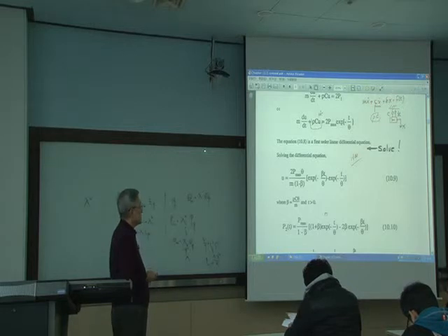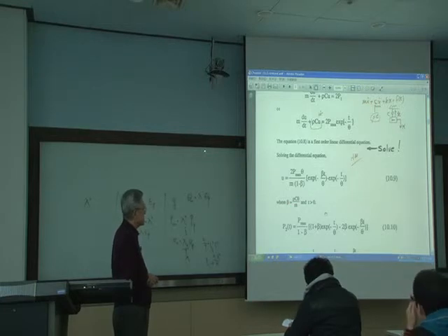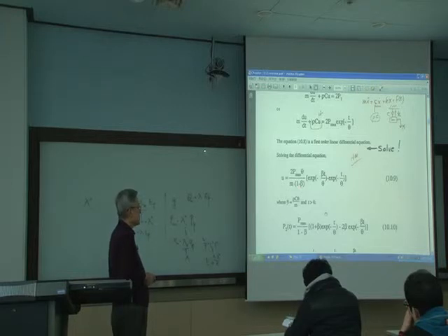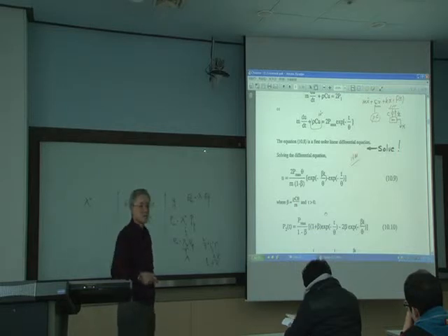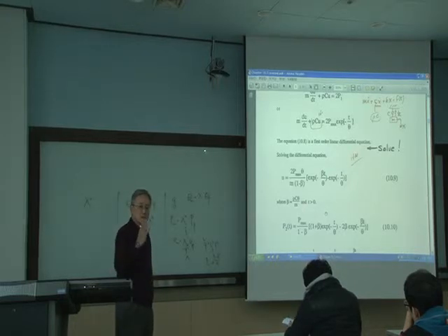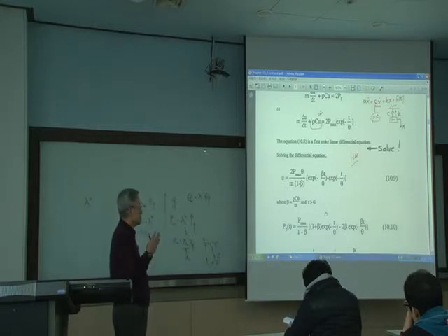Now, one value, beta, is defined in the process to express the solution a little more simply. This beta is rho C theta over m: the impedance, and theta, the decay constant, over m. Rho C is a constant for the water, and m is a constant for the infinite plate. That's mass per unit area.